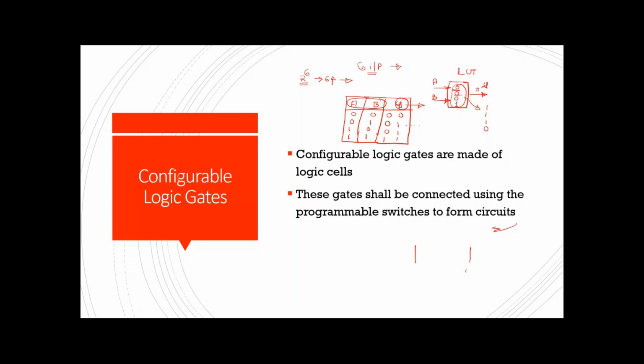But here, once you write the RTL, that VHDL, most of the mapping, right? So whatever the logic inference will be there from that VHDL or Verilog, that will be taken care of by the tool to map to these memories. So these lookup tables will be not just one or two, millions of lookup tables will be there in the FPGA, right? So that mapping or configuring that FPGA to act like the circuitry you want will be taken care of